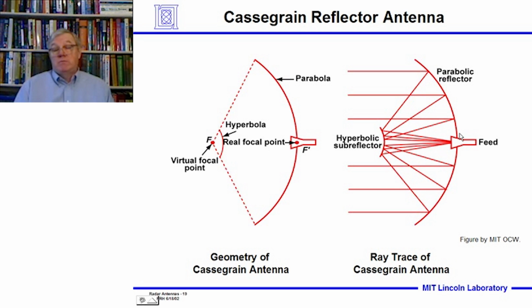One thing I didn't point out is that at very high frequencies, the loss for 100 feet of waveguide at say 3 centimeters can be as much as 7 or 8 dB, and at say L band, which is 23 centimeters, it can go down to the order of less than a dB per 100 feet of waveguide. So the attenuation in the waveguide can be a significant factor in wanting to choose a Cassegrain feed. Okay? Now, what do these look like?